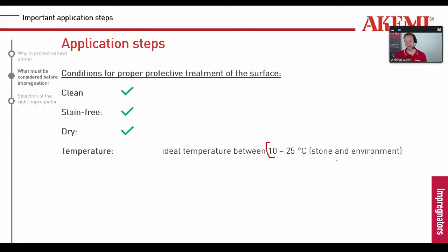So here we recommend, after 5-10 minutes, depending on your stone and your temperature, to do a second treatment, wet in wet. Don't let the first treatment dry. You see it starts to dry in some areas, then you go again directly with a second coat on top of it, so that you get about the 15 to 20 minutes reaction time.